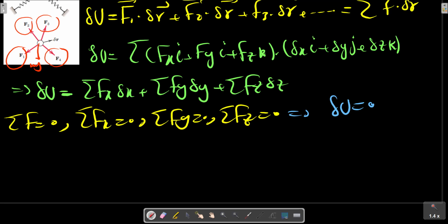This condition of zero virtual work for equilibrium is both necessary and sufficient, since we may apply it to virtual displacement taken one at a time in each of the three mutually perpendicular directions, in which case it becomes equivalent to the three known scalar requirements for equilibrium.